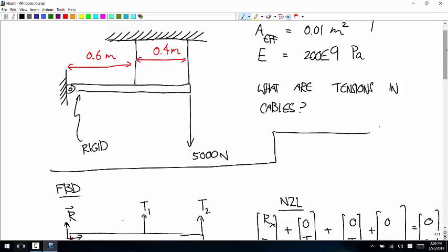We're also going to assume that it doesn't go up or down the wall, and so our assumption is that this point of the rigid body stays exactly put, and that this is rigid, and so as these deform, we're going to get the endpoints of these two cables following a line. Like if you did a big deformation, it would be like this, you know what I mean? It's always going to make a line from this point and this point through the hinge. That was not clear wording at all, but you know what I'm talking about?